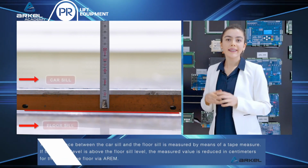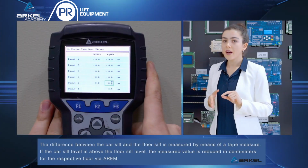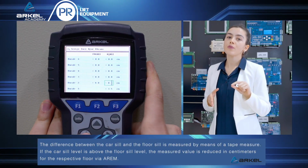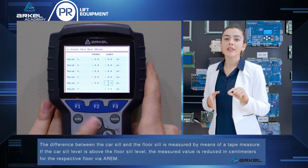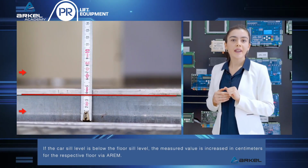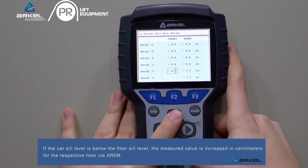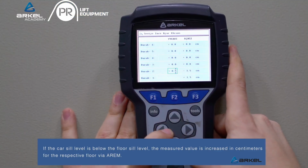The difference between the car sill and the floor sill is measured by means of a tape measure. If the car sill level is above the floor sill level, the measured value is reduced in centimeters for the respective floor via RM. If the car sill level is below the floor sill level, the measured value is increased in centimeters for the respective floor via RM.